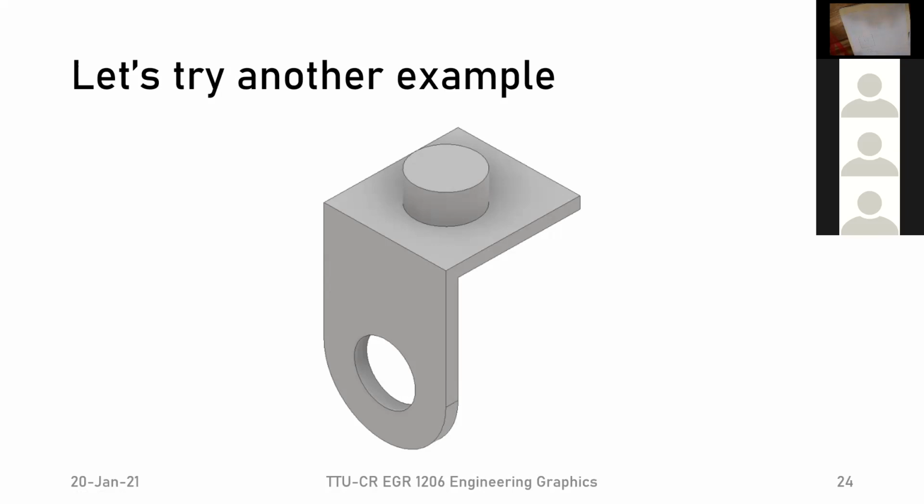Whenever we do our three orthographic views, it's always the same sequence. The front view is down here, the bottom left, above it is the top view, and to the right side of it is the right view. That's always the combination that we want to have. We always want to have them aligned in the vertical direction, so that the line that's here has to line up with the line there, because they're the same line. And then to the side, we want to do the same thing.